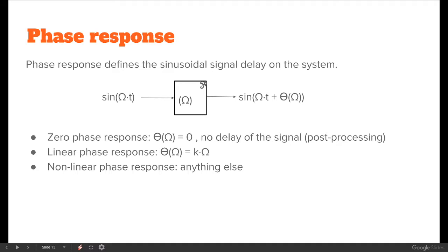Think of a signal that goes into a system. Now I have it as a sinusoid signal. So you have sine of, I will just mark it as continuous time, it doesn't make much difference. Mathematically, it goes through the system. What goes out is the amplitude response at that angle times sine of omega t plus the phase shift at that frequency. Okay, phase shift.